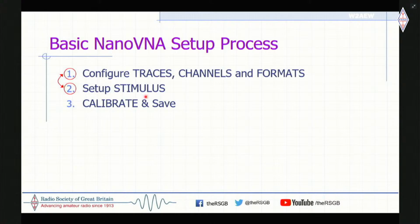So if you're always going to make just an SWR sweep of an antenna over a frequency range, set up those channels and traces, set up that frequency range, calibrate and save it. And then as soon as you recall that, all of this is already done for you. So you only really have to do it that one time. All of these things are saved as part of that calibration save slot.